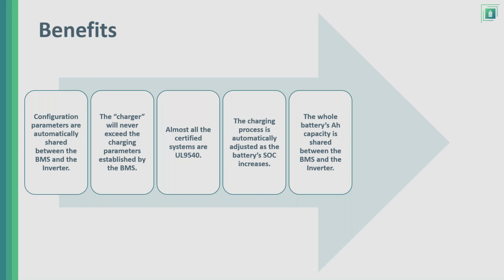So if you decide that you need 4 or 5 batteries, in the case of an eFlex 5.4, and you need a 20 kilowatt battery bank, you will probably have to have 4 of them in parallel. Parallel in terms of power consumption, yes, but also in parallel in terms of communication.